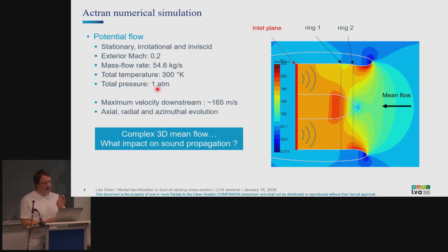But since we consider in this simulation conservation of the energy, of course the total temperature and total pressure remain the same inside the duct, but with some part of it in kinetic energy, so the static temperature and pressure would be less inside the engine. Yeah, exactly. It's the boundary conditions on how to set your simulation.